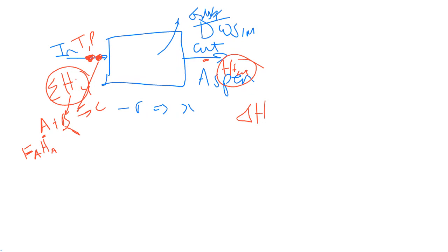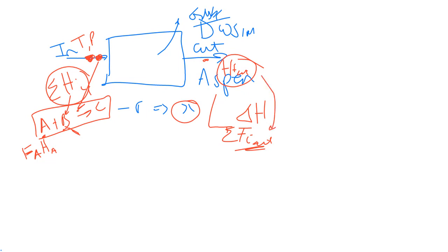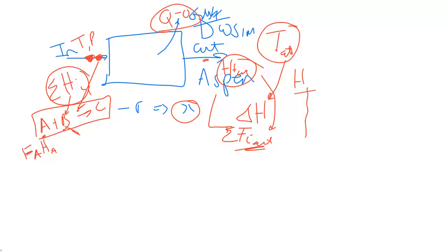Similarly, if you specify a specific conversion linked to a reaction, it can calculate your outlet product spread. So it will know what your outlet flow rates look like, and it will then do an energy balance. If you tell the system it must be adiabatic, you specify Q to be 0, and it is going to do a trial and error for the outlet temperature, T out, by calculating H values and looking them up in a table.